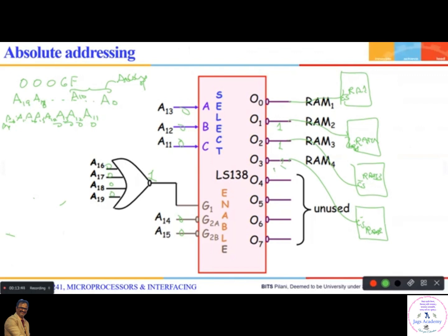The problem comes when the microprocessor is 16-bit and can take 16-bit data, but your memory is capable of giving only 8-bit data. During that time, we have to completely modify our entire design. Instead of using one memory chip, we have to read from two memory chips, because the microprocessor can read 16 bits of data.